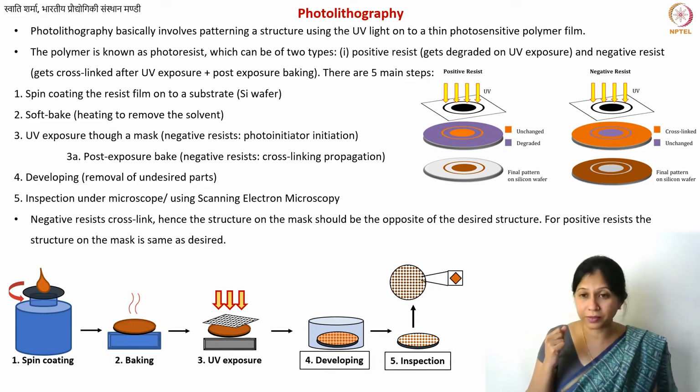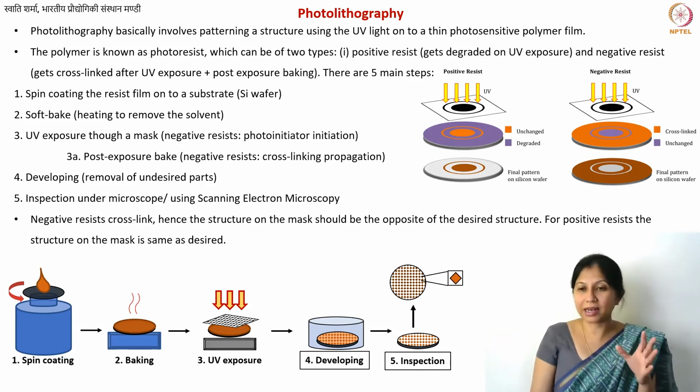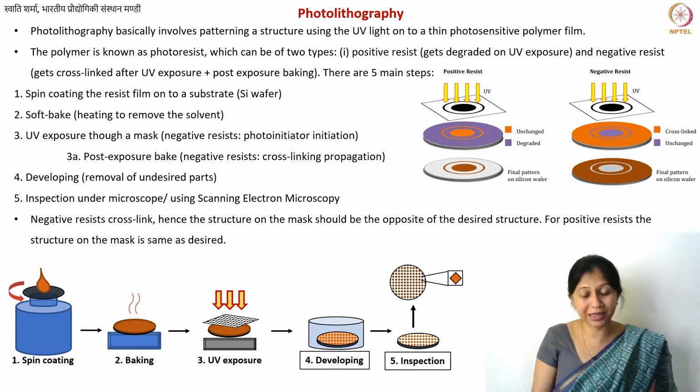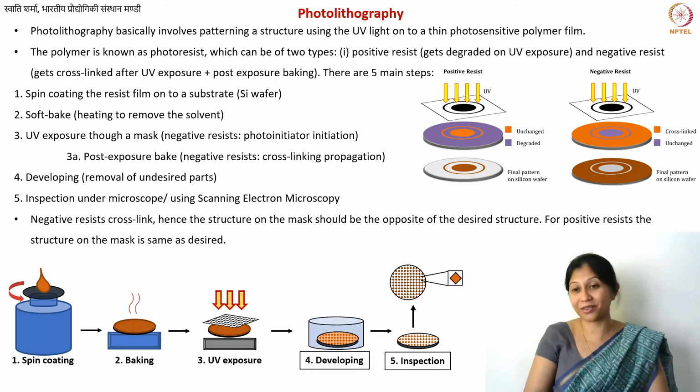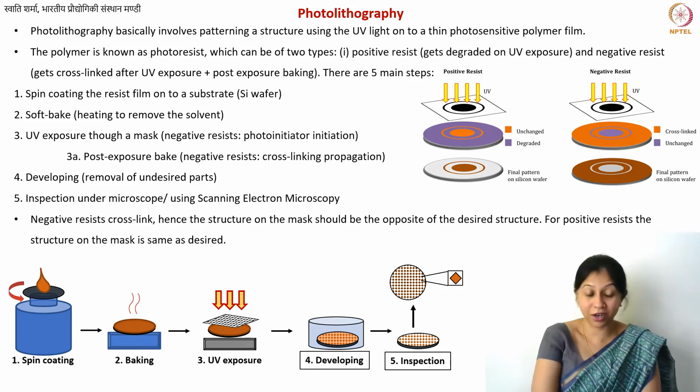But why don't we do it? Number one, is it worth it? It depends on our application, how high you want to go with electrical conductivity. But even if electrical conductivity was very important to us and heating the device further would be better, the problem here is that you have a silicon wafer. You need to make sure that your wafer, your substrate, does not melt and does not get deformed, even by thermal fatigue. Now the melting point of silicon is 1410 degrees centigrade.